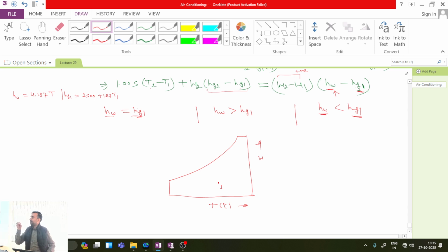I am adding water vapor with the enthalpy content of water vapor equal to that of the enthalpy content of the gas. Okay. In this way, the temperature of the medium will not be actually changing. Okay. I will be finding that the process will be something like this, a vertical line, which may become a pure humidification process.